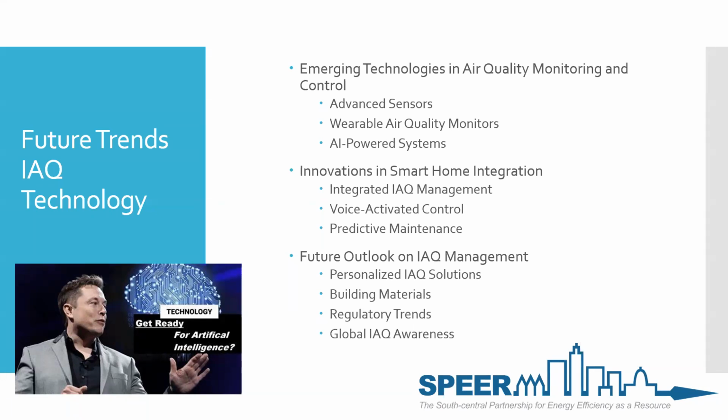So smart air purifiers with advanced filtration are also there. It can start telling you when the filter is clogged. It can read static pressure. It knows the differential between before and after the filter, and it will pop a sensor and say, filter needs to be changed. It may only be 45 days after you've put it in, but it knows when it needs to be changed due to air restrictions, not waiting for you just to change it every 6 months.